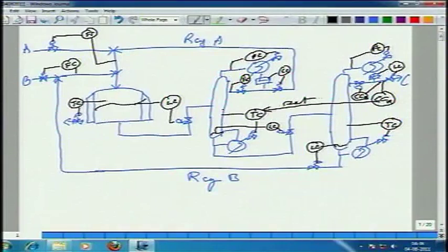If too much A is leaking down, no matter what you do, you have to live with an impure product, because that leaked A is bound to end up in the top, because it is the lightest component. Yes or no? Okay. So, therefore, I am controlling the A composition by adjusting the temperature set point in the recycle column. I am controlling the B impurity in the product stream by adjusting the reflux.